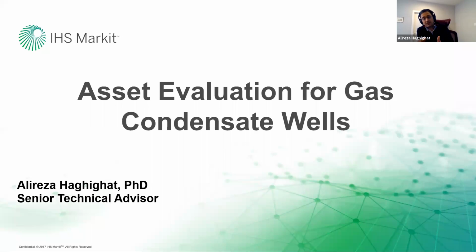If your reservoir gets below the dew point, you form some condensate in the reservoir and you leave some condensate in the reservoir, and probably you bring some different gas composition to the surface and you recover less condensate. So in order to be able to model this process, you need to consider the liquid dropout curve. You need to have a reservoir model that tells you what the pressure is at each time during the performance of the well, and then you'll be able to model the condensation process.